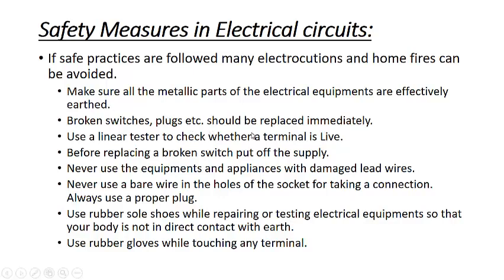Broken switches, plugs, etc. should be replaced immediately, because they may result in overheating, and finally in fire. Use a line tester to check whether the terminal is live when you do testing, repairing or maintenance. A line tester is a good thing to use, because you'll be able to understand which wire is live and which wire is neutral.